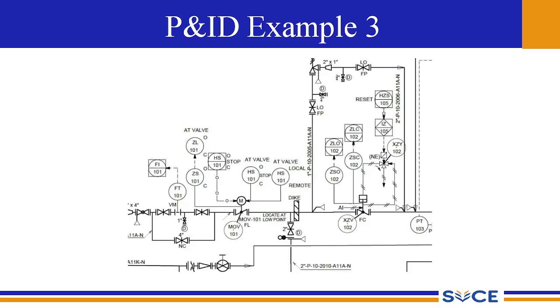You read the P&ID from the left direction to the right direction by following the main process flow arrows. After that, you look at the instrumentation corresponding to that particular line, and you identify the cluster of instruments for that particular control loop. So by that you can comprehend the necessary information related to that diagram.